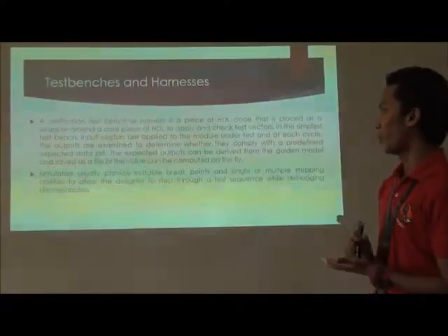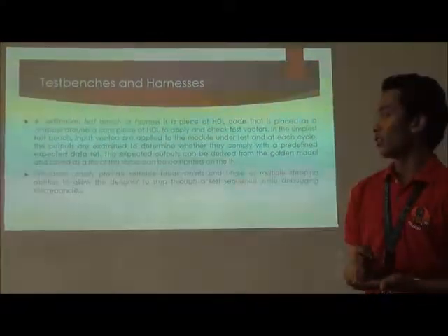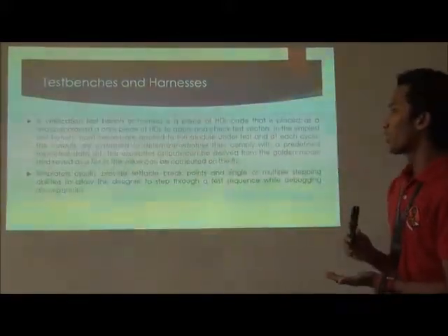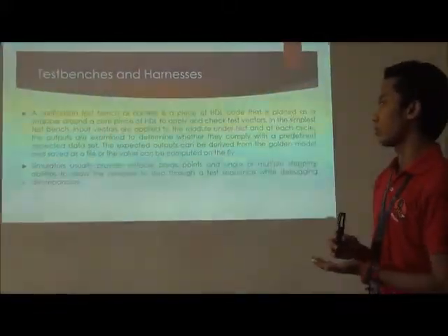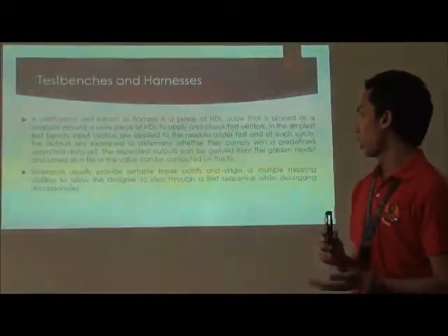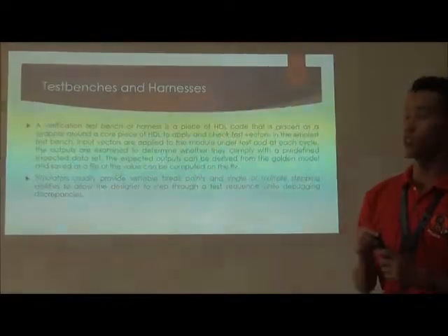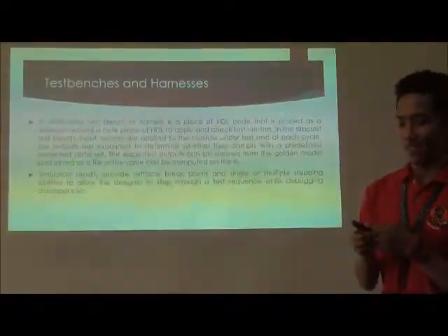So the expected outputs can be derived from the golden model and saved as a file, or the values can be computed on the fly. Simulators usually provide settable breakpoints and single or multiple stepping abilities to allow the designer to step through a test sequence while debugging discrepancies.